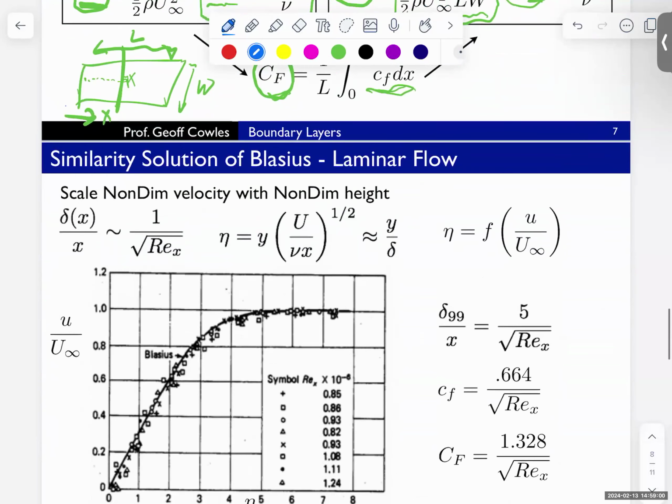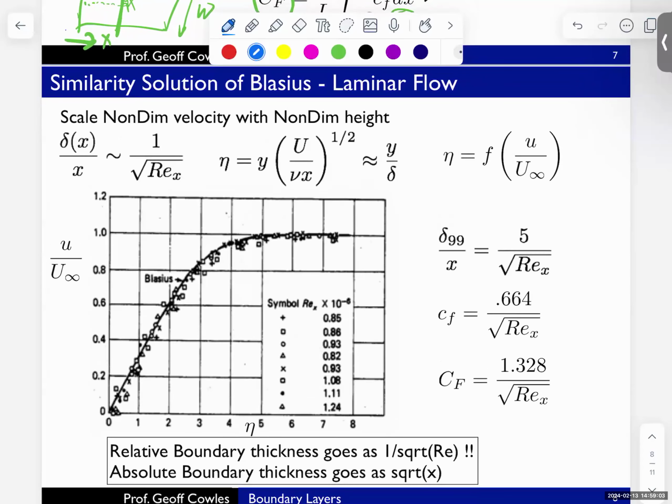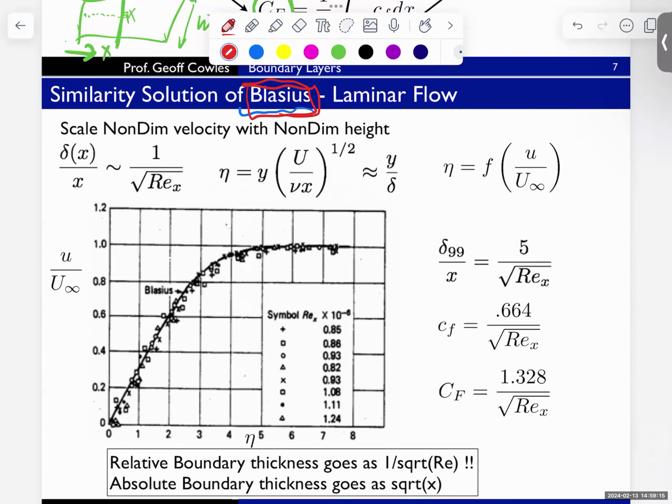Now, this whole idea of a boundary layer growing on a plate was examined by several folks, including most notably Blasius here. So this is early 19-teens, I would say, 1915, somewhere around there. He was looking particularly at laminar flow moving over a plate, making measurements, adjusting flow speed, adjusting the plate length, adjusting the fluid viscosity, and seeing that there was a similarity, similar to what Froude saw. They knew there was a similarity to things, meaning when what they called the Reynolds number was fixed, it seemed to fix all the properties of the boundary layer.